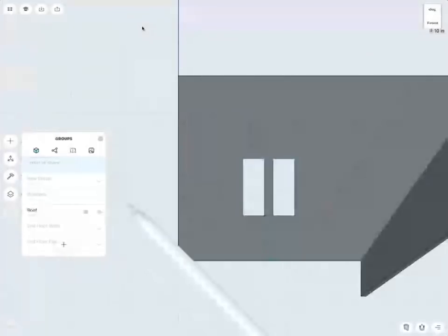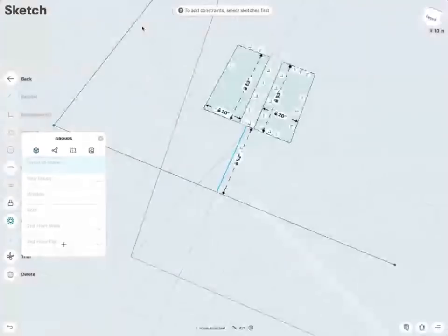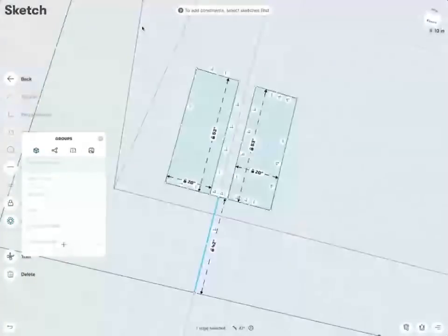If I then draw a line until it hits an edge, you can see I can project these edges into my sketch. And then that helped me to establish the height dimension and then create the opening for the windows. So the window up here are actually at a rotated position. This might look complicated, but pretty much is exactly the same very easy process as before.